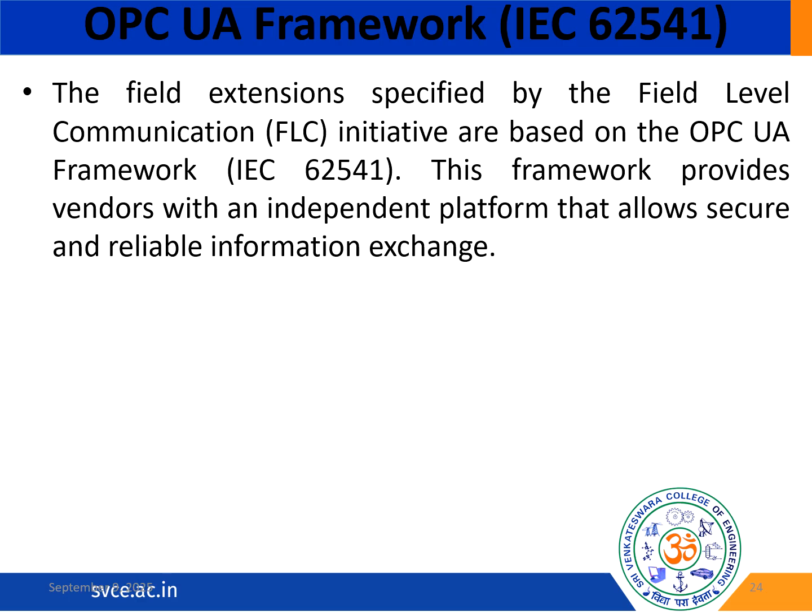So OPC UA can run on a dedicated client and server relationship. In a publish-subscribe scenario, the server publishes data to the network, and the client who subscribed will receive the data.